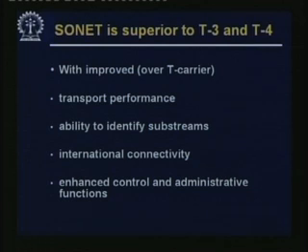And SONET is actually superior to T3 and T4 etc., the T carriers. T3, T4 are still in use, but nowadays they feed into SONET, whereas earlier they used to feed into PDH. These are particular rates which existed, and their specification left something to be desired because of this lack of synchronicity, in handling signals from different sources, mind you.